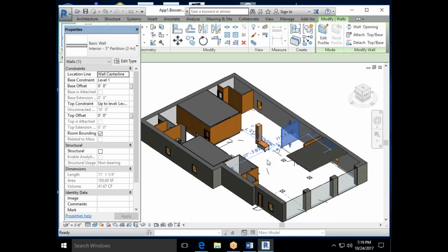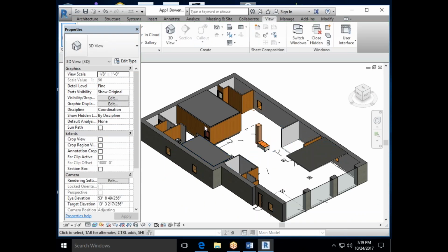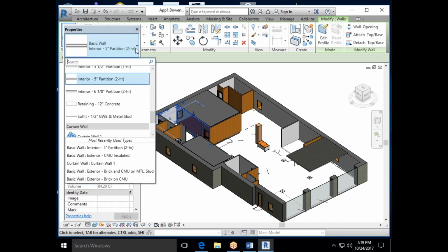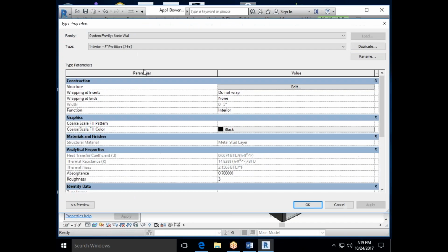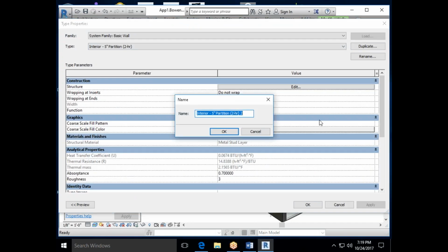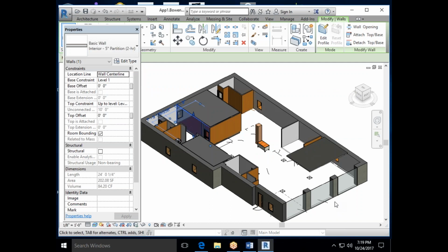Okay, so here's something I wanted to get out for tonight. When I said we could do generic walls, that's true. Now wherever you use those generic walls or certain types of walls, if you apply the material that way, like how I just did it, it's going to change it where every instance of that wall is placed. So what we could do is, if we don't want it on this wall, we could create like a duplication of that wall under the edit type and duplicate it and change the material back to whatever we want it to be, and then individually duplicate the walls out so that it's the same thickness, but it's just changing the material on top. Does that make sense?